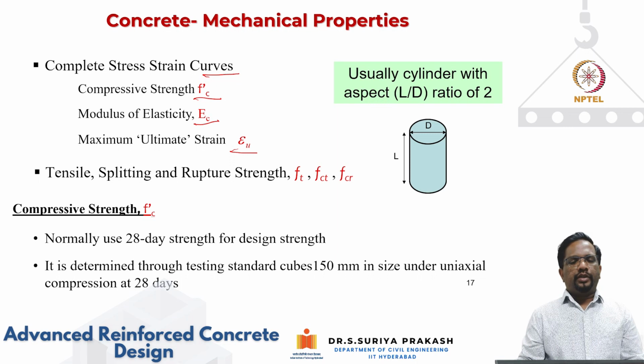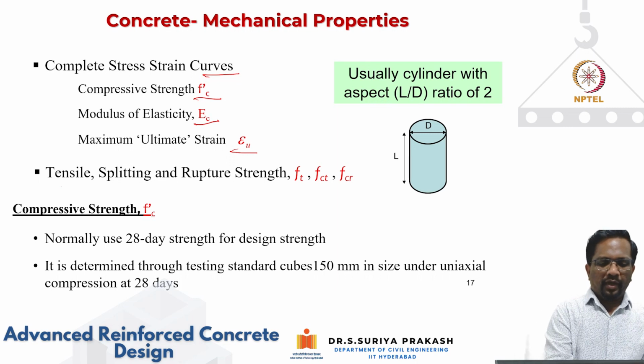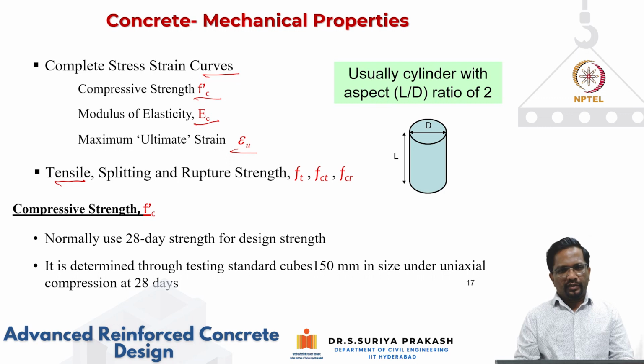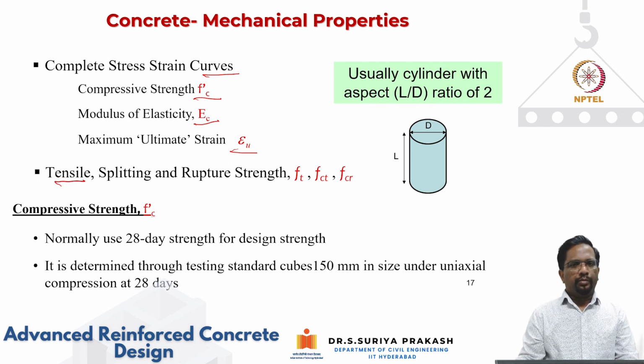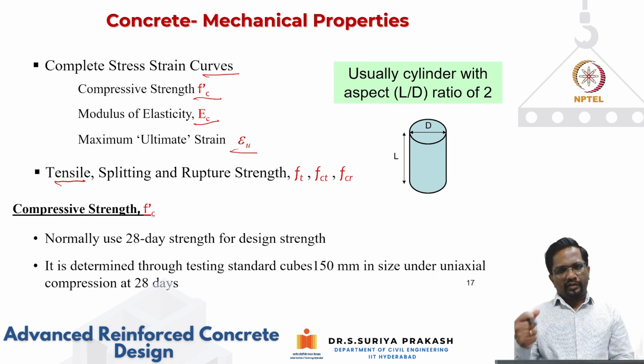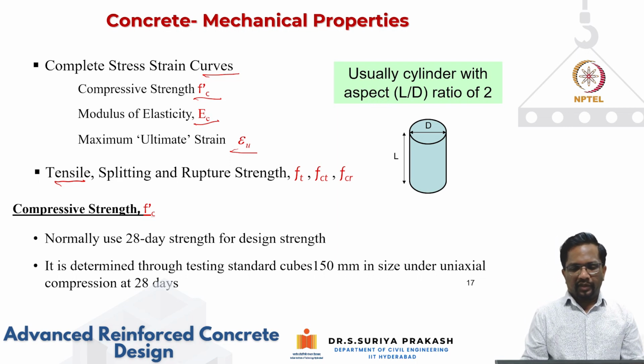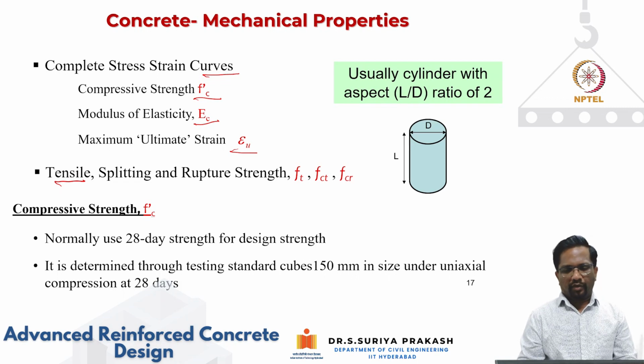In addition to that, for flexure, and especially for prestressing applications, we need to know the tensile strength of concrete. Concrete tensile strength can be measured in multiple ways. You can do a direct tension test, which is actually difficult, or a bending test to get the bending tensile strength, or something called the Brazilian tension test, also called the splitting tension test. We will talk about that.